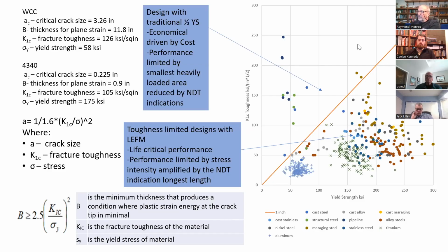For this graph with fracture toughness, one of the reasons you don't have to do much in K1C is that if I just use 50 ksi per square root inch, I'm probably okay. I probably don't need to do a number. And this is one of the odd things that we don't do very much lately, is we think in terms of science. And so we worry about whether I'm here or here. And it doesn't make any difference because the variability of the test is bigger than that.